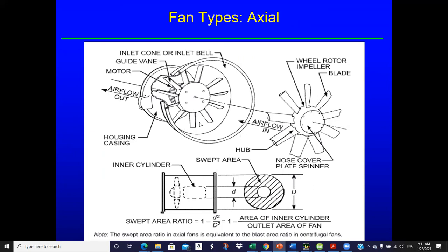We'll see all these technologies listed in a second, but a lot of times we look at going to variable frequency drives to do variable speed control, and you can certainly do that on a centrifugal and an axial fan. Or on these axial fans, you can go to variable pitch control. The efficiency of the two, the VFD and the variable pitch, is pretty close. I've heard stories about maintenance issues on the variable pitch. I don't really have any direct experience with that because I've not seen all that many of these.